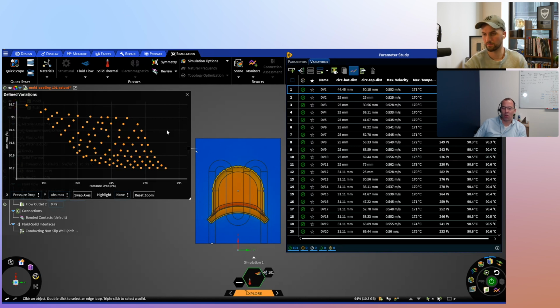And then the third aspect of a secondary deep dive on this could be design for additive, right? This particular geometry, I simplified it, but we can talk about how I then take this if I cannot manufacture it any other way. It's so complex. The conformal cooling channels go all around the part. So complex, I have to do additive. There's a simulation workflow for design for additive for metal, which we have as well. So there's a couple of different ways, Jousef, that we can take this model and move forward in a couple of different directions. I'm wide open to whatever.